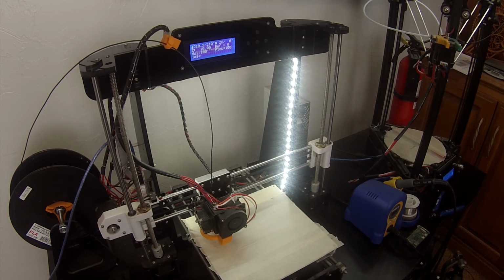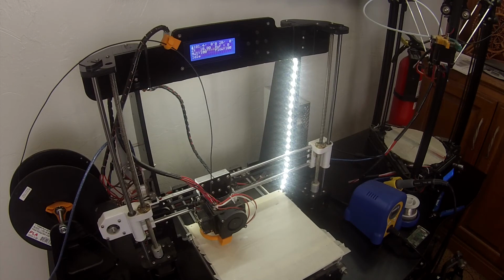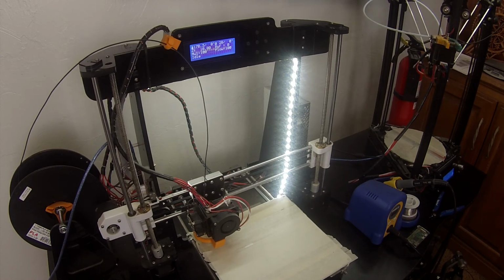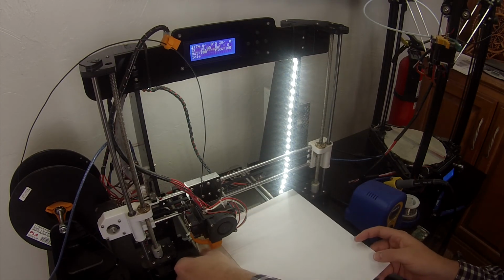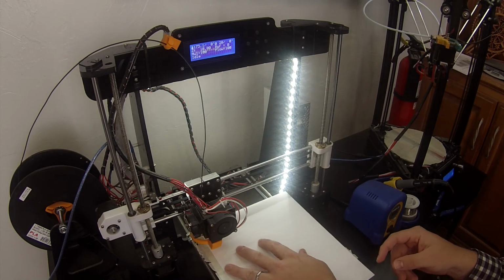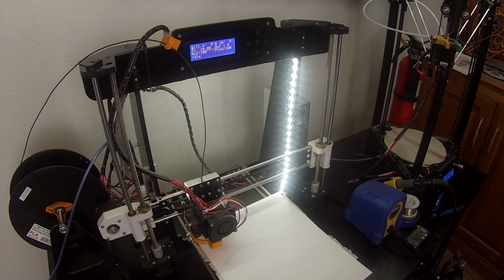The best way to do this is the same way we check for tool height on a CNC machine. So first of all, make sure your extruder's off. You don't want to start burning any pieces of paper. Mine was actually quite warm right now. It's still up at 210 C, so I'll have to wait a little bit for it to cool down. What I typically like to do is take the extruder to each corner. That also happens to be where this bed has adjustable screws beneath the bed. And I place a piece of paper down on the bed, and you're going to lower the print nozzle down on that paper to the point where it pinches.